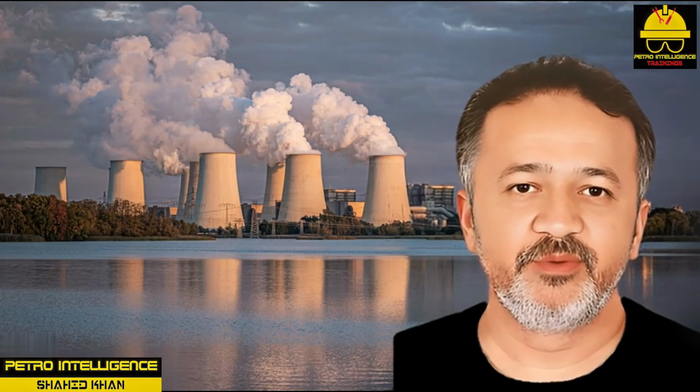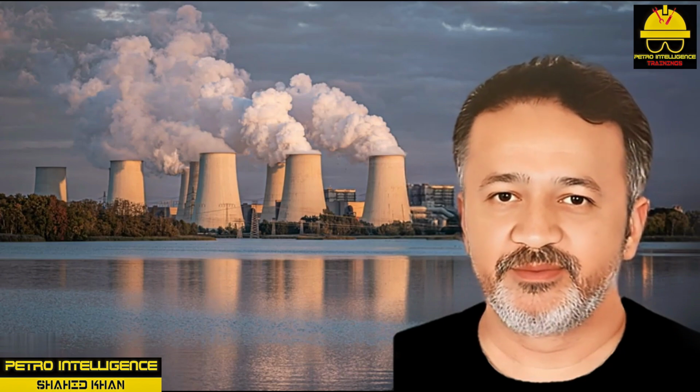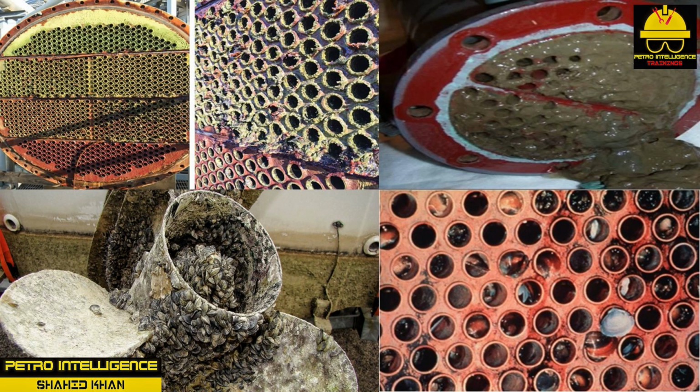Microorganisms, chlorine and bromine concentrations. Cooling towers provide the perfect breeding ground for microorganisms since they are exposed to warm water and sunlight. Microorganisms form slime that can build up and restrict water flow and conductive heat transfer. Biocides such as chlorine and bromine can control the growth of these organisms.